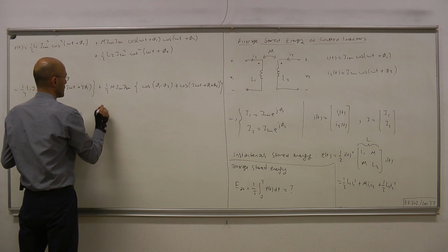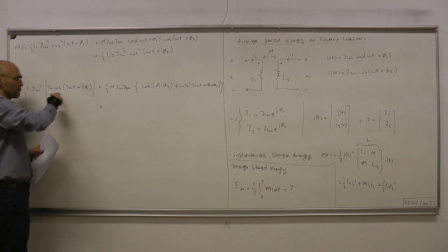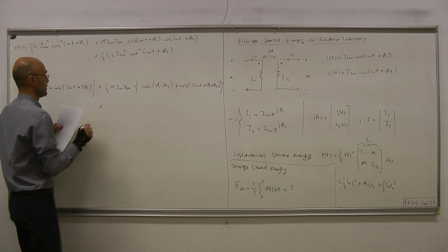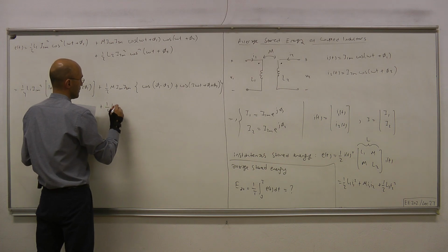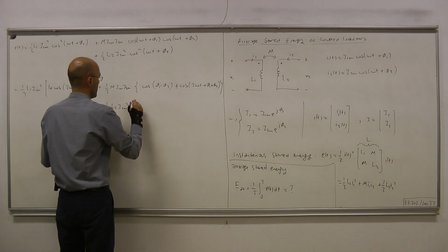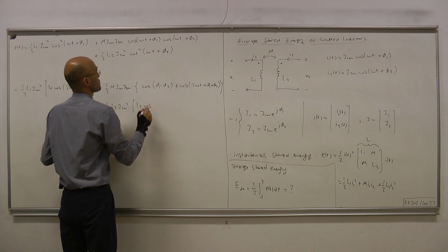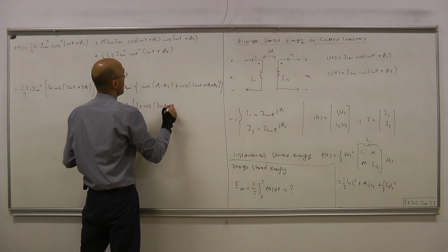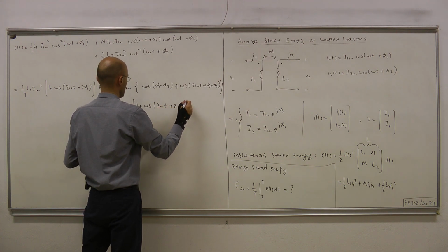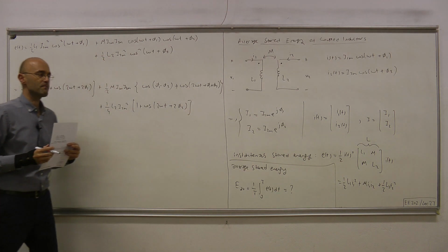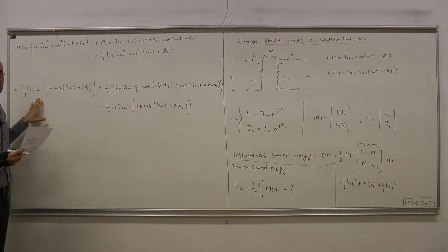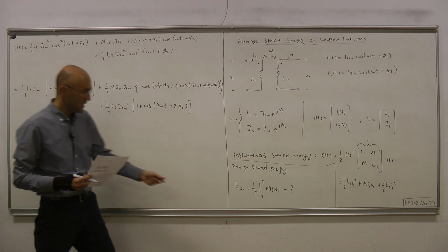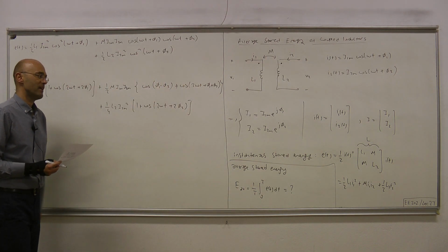And finally, we're going to apply the same trick to the last term as we applied to the first term. So what we have is 1/4 L2 I2m square, 1 plus cosine of 2 times the argument, 2 omega t plus 2 phi 2. This is E of t written in a slightly different way, but that slight difference will make life very easy when we compute that average.